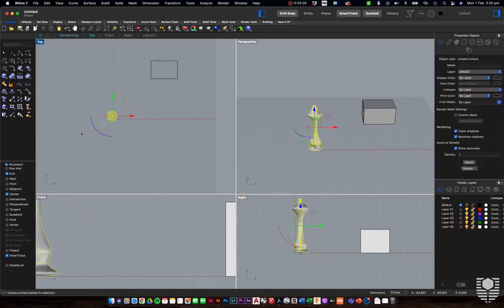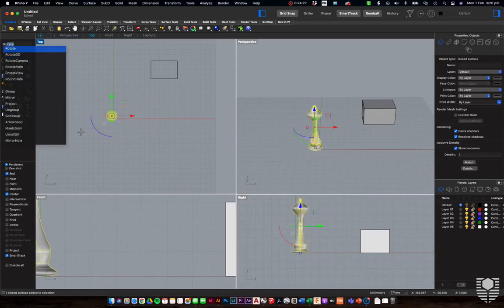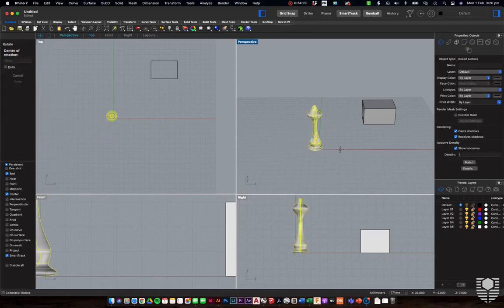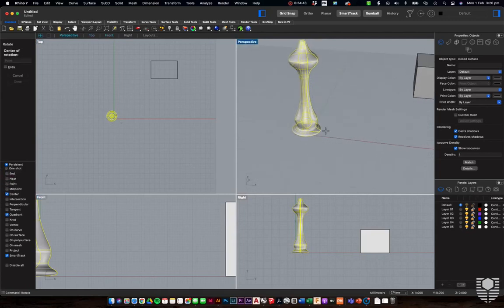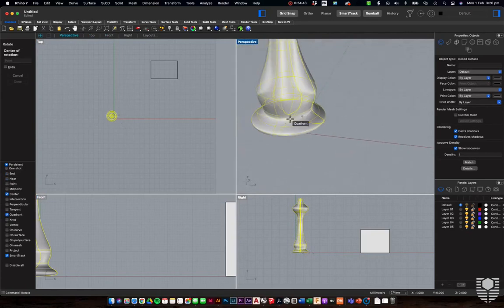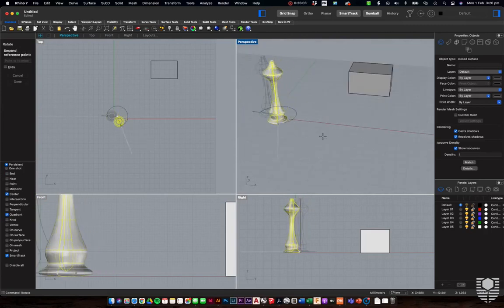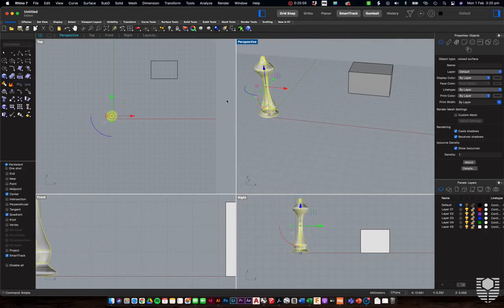Again, we've got the long form way to do this too, so if we go rotate, it's going to ask for the center of rotation. So I'm going to come down here. This time I'm going to click, actually I want quadrants on the outside. Near and okay. So now I can get my quadrant here to the other side, and I can rotate around that specific point.